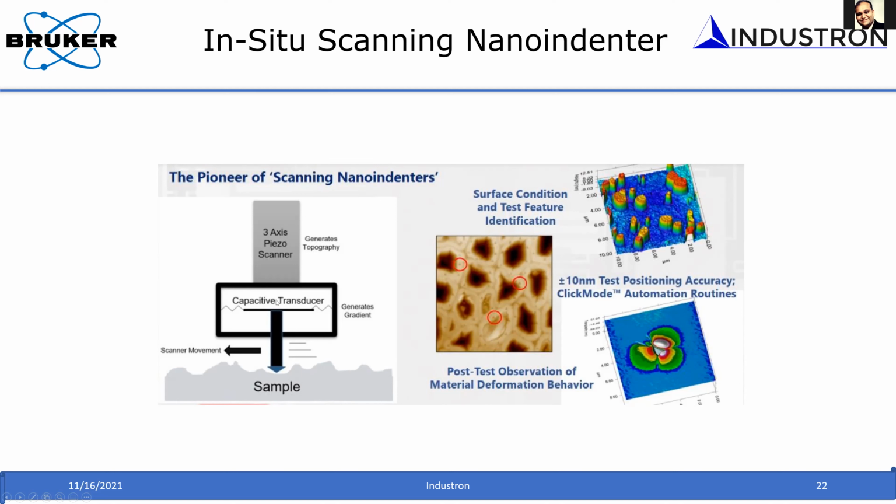If you measure that change in height as you scan, line by line, you can create a profile. By constructing those profiles into an image, you can get a three-dimensional image of your sample surface. You can use this technique in situ to measure the surface topography in three dimensions at high resolution. This is similar to an atomic force microscope, but at a slightly higher scale.